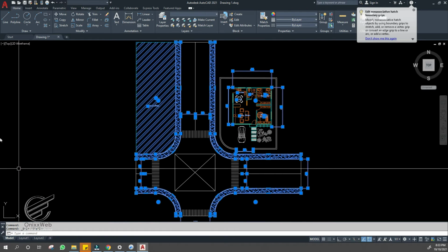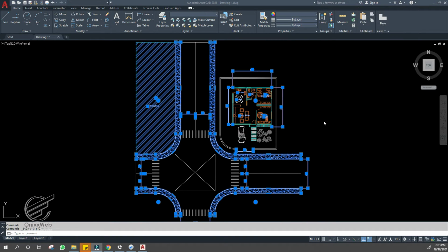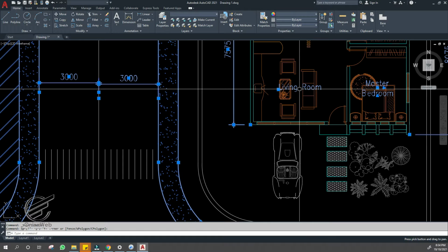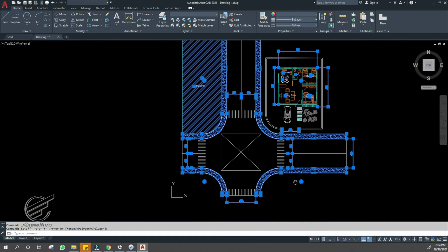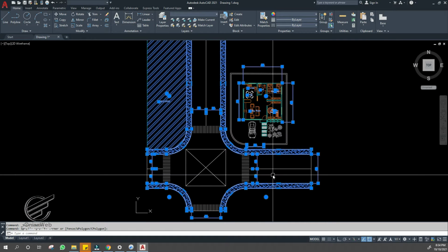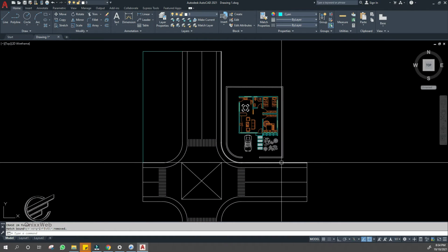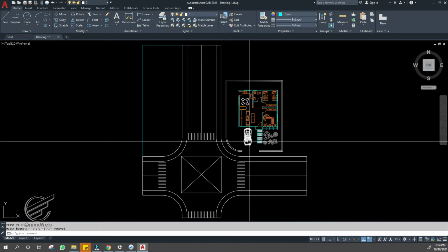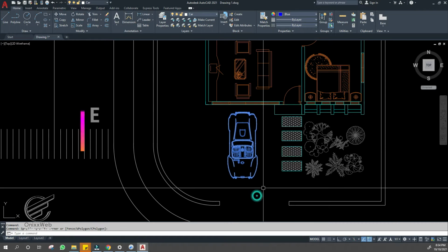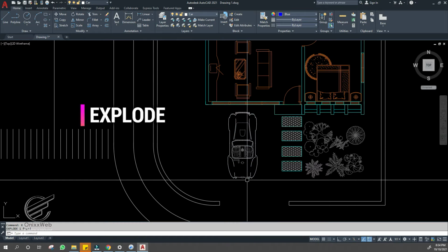For example, in this CAD file, we have here the presence of dimensions and hatch. What we are going to do is to delete them and minimize the drawing area for export. If ever you want to import any unsupported CAD elements into SketchUp, try exploding those elements in CAD so they become primitive CAD drawing elements that SketchUp does support.